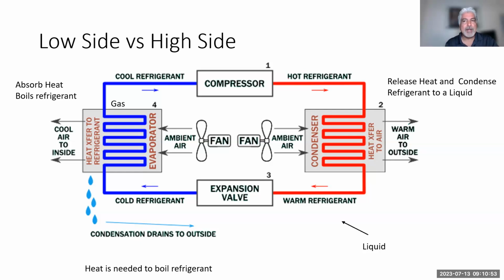Let me give you the scenario. The system takes 2 pounds, let's say, and you charge the refrigeration system and it won't take more than 1.5. It won't take the 2, but the specifications say it takes 2 pounds. Why would it not take the 2 pounds like it's specified? It isn't that there's something stuck in there. It means that it's restricted. Either the condenser or most likely the evaporator has a restriction in it. One of the passages is clogged, most likely from the desiccant or metal from the compressor, but most likely desiccant from the receiver dryer or accumulator might be stuffed in there.